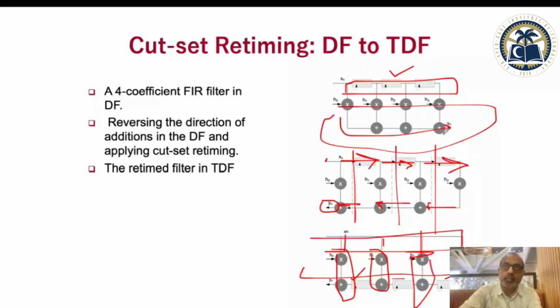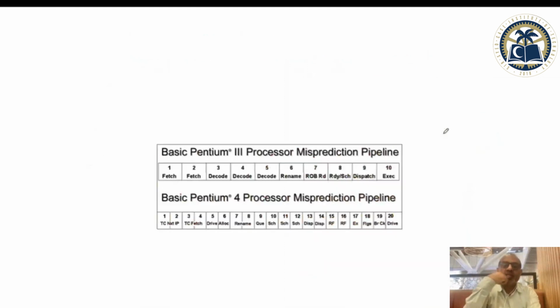And as I mentioned earlier, sometimes you let the synthesis tool do this for you. I am not sure if we will be able to demonstrate it to you today or not, but we would definitely show you that if you enable the retiming, it will do the retiming for you. But then the synthesized code would have a bit different architecture, where the registers that you place in your Verilog code would appear somewhere else in the synthesized code. But sometimes you really don't care.